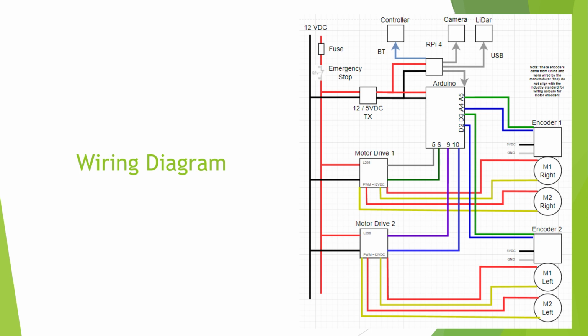The encoders, there's only 2 encoders, one on each side of the mower. We don't need to get encoder positions off. We could and do some weird thing, but we're not. There are 2 encoders, one on each side. They come back to the Arduino's input pins, the appropriate ones. So D2, D3, A4, A5 is what I've used for that.